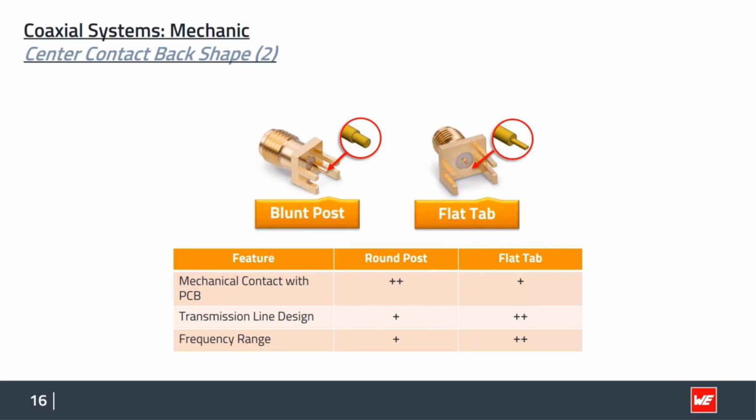And also, if you solder it, take care not to use a lot of solder paste because this will bring you additional parasitics on the capacitive side, which, let's say, negate or which limit then the positive impact of having this really small tap on your transmission line.